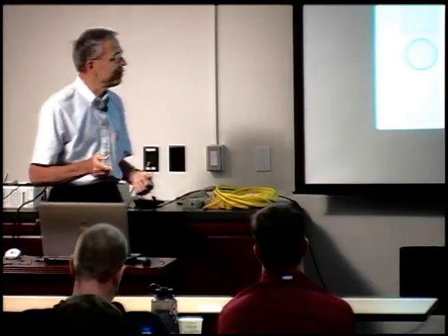Now, if you look at the overall way that we've approached it, and play professor a little, as I used to do, what we've done is we've said, okay, you get your loads, factor them up, and that tells you how many piles you have. And then you figure out how long they have to be, and deal with the driving.